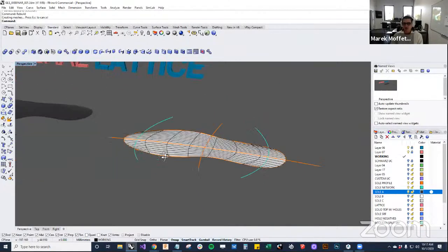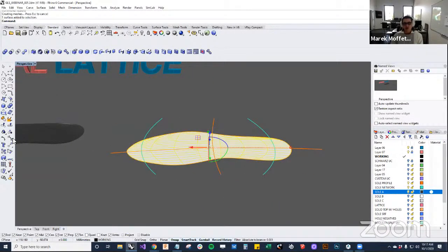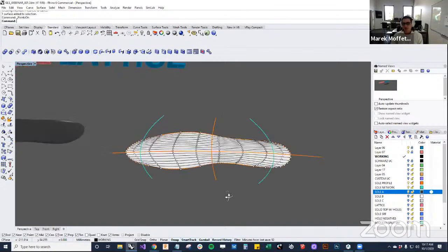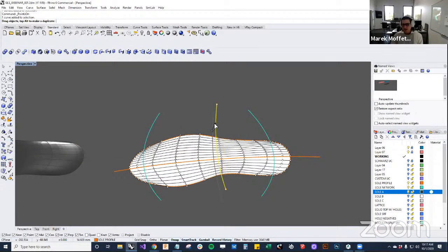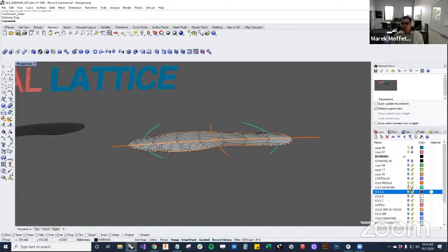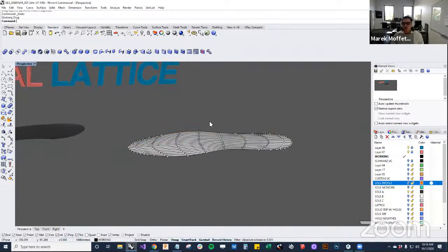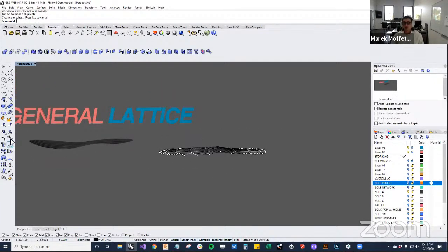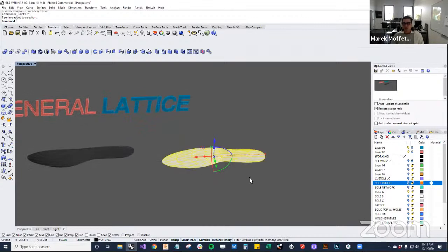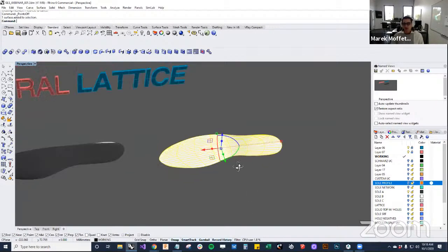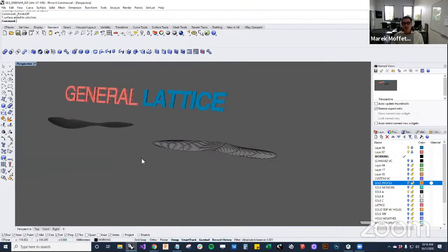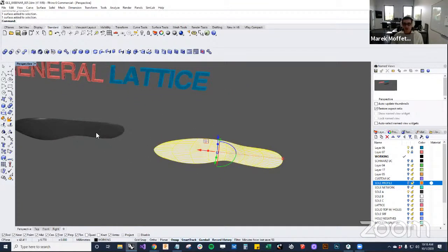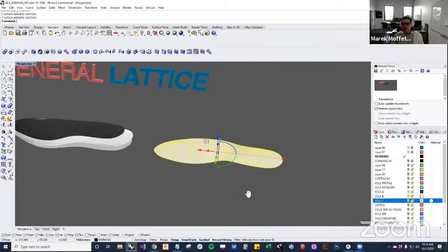And so with this technique, you can turn points on and you can start to manipulate this structure. And so if you can imagine you wanted to make a sole that matched a certain profile, or just even wanted to add an arch or some organic shape to that, you can start to manipulate these points, and rebuilding them to an amount that allows it easier to manipulate can be done. But that's essentially the technique I have used to create these 3 surfaces.